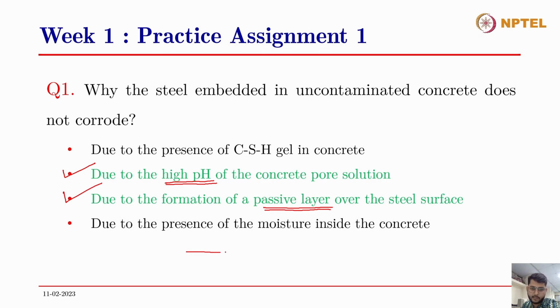So typically what happens is, let's say this is a steel reinforcement which has some ribs. The steel reinforcement has a passivating layer around it. Essentially, the steel or the metal forms some oxides when it comes in contact with the surrounding environment, and these oxides can also be called the initial corrosion products.